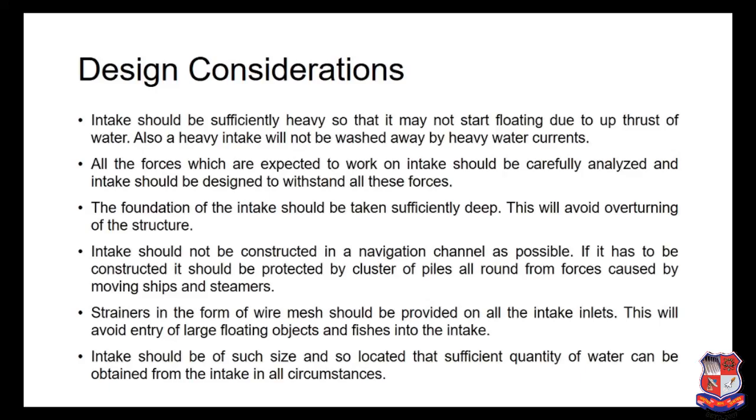These are certain design considerations for the intake. This intake should be sufficiently heavy, right? We know that we are providing the intake in water, so uplift pressures of water will be there. Water will exert uplift pressure on the intake. So it should be sufficiently heavy so that it may not start floating due to the upthrust of water.